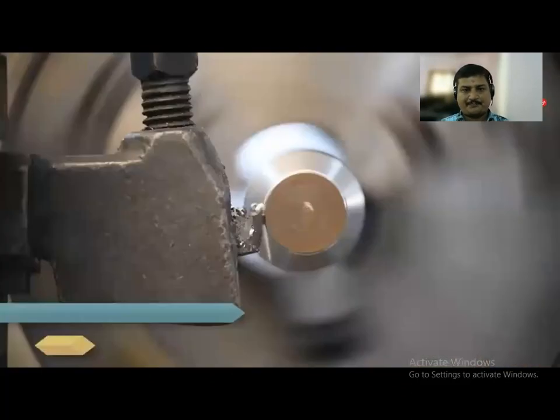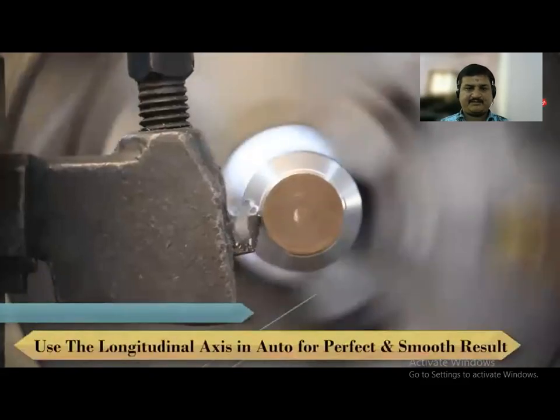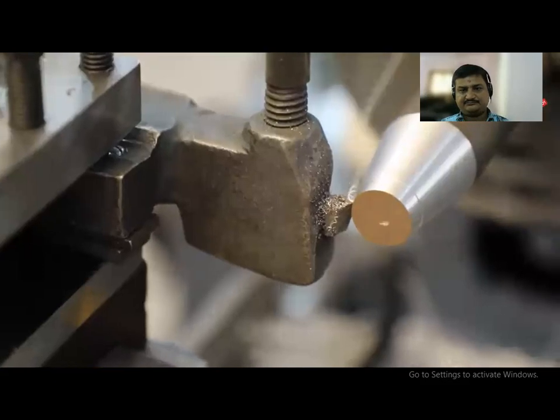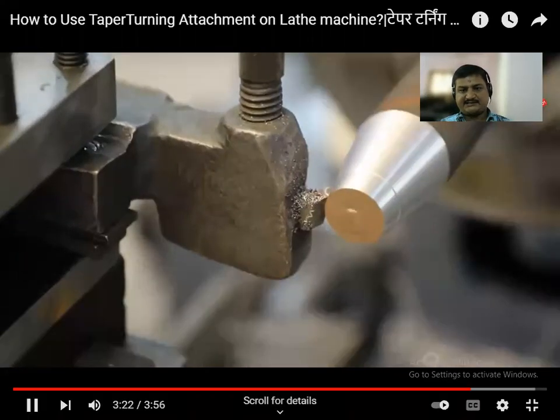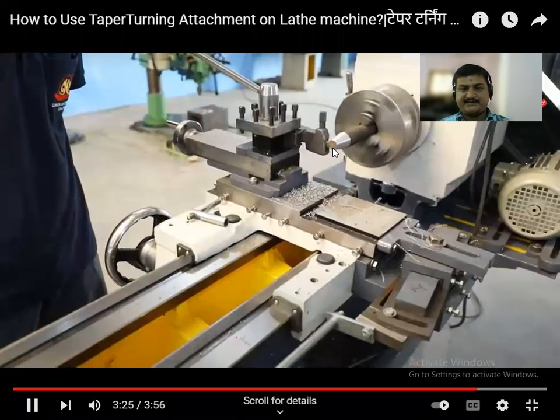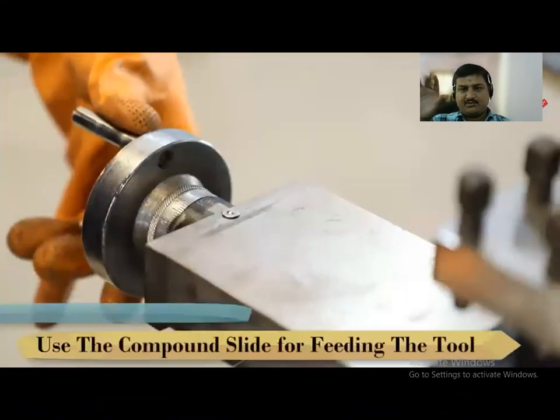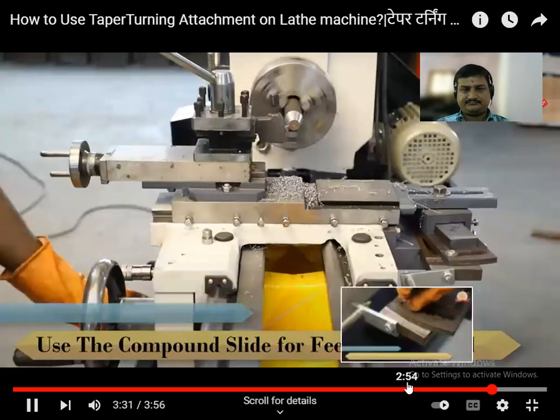For good results in taper cutting, always use the machine in auto feed. Can you see the taper turning now? Yes, sir. The turning is happening, but here at the front side less diameter is there, and at the back side more diameter is there. For tool feeding you can use the compound slide.